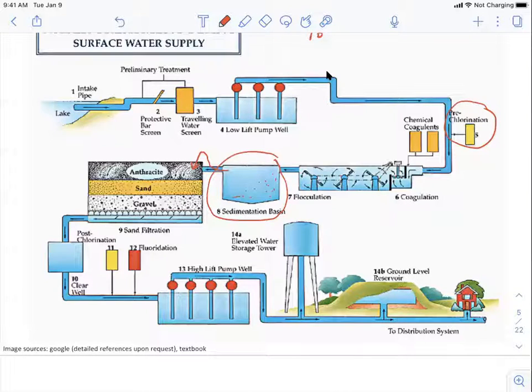They just collected some sand, and for their branch of water where they take the water out, they built something like a dam. You collect some sand in there, and the sand filters out the suspended particles inside. What you get out of it is the purified water. So sand filtration has been a common concept for water treatment for quite a long time, and I would say people are very familiar with how it works.